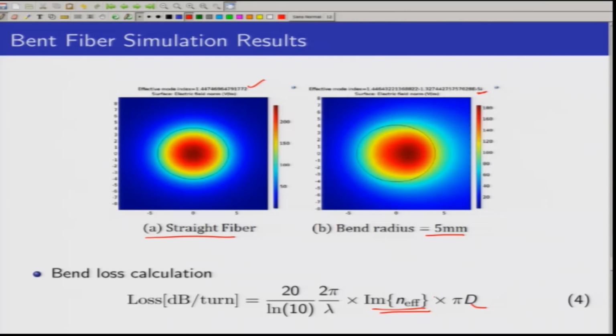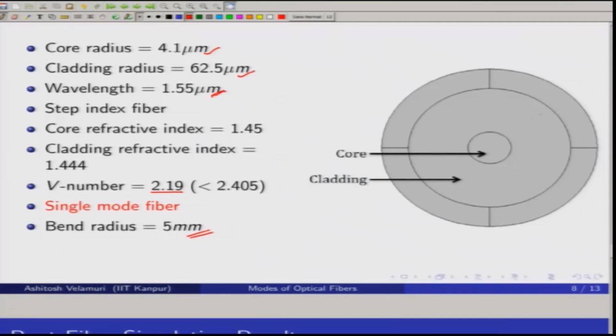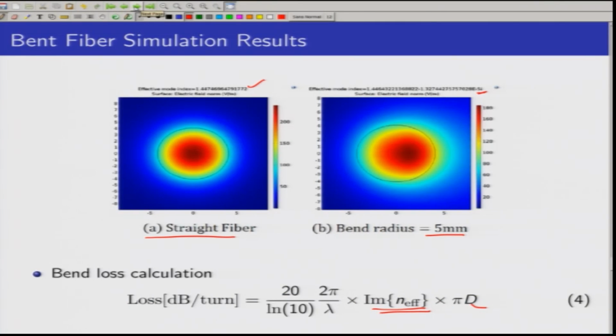One more important point that we need to see here is, if we observe, there is a third layer here which is a PML, which is a short form of perfectly matched layer. Why do we use this layer? Is this really important? As we have seen here in the slide, there is some radiation happening from the core and this radiation will pass from core to the cladding.